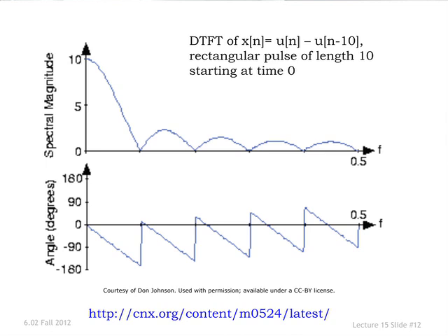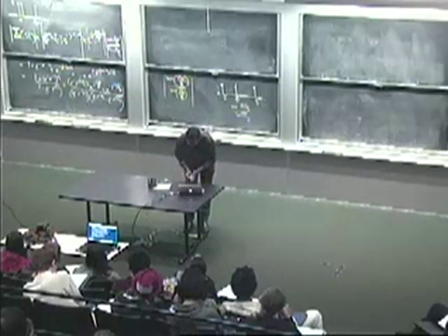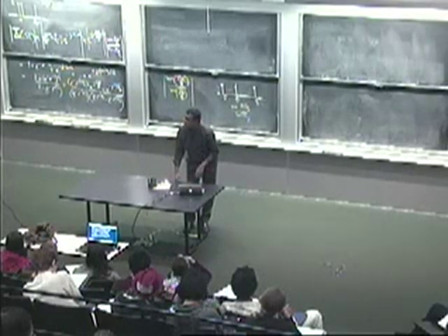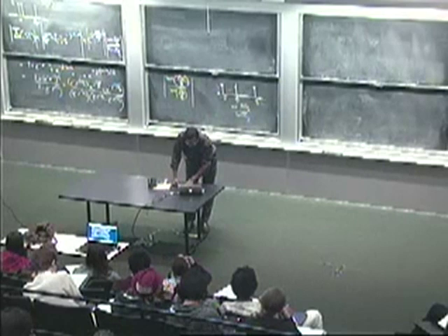And what you're seeing here is a linear phase characteristic, except every time you have a flip in sign, you jump the phase by 180 degrees, right? When you change the sign of something from a plus to a minus, that's like adding 180 degrees to the phase or subtracting 180 degrees from the phase. So you can spend time on all of this and make sense of it. But the basic idea is that you get the sinc-like distribution in frequency.